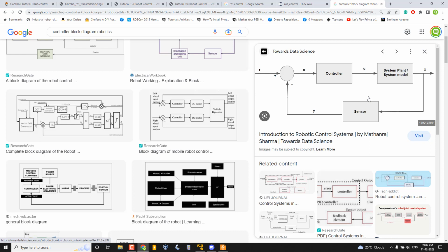You can try with your hand. Currently your hand is in one position, and if you quickly move to another position, that is not the desired kind of motion that we want in robots, right? If all the motors are moving very quickly, the robot will be shaking, right? So what we want is a smooth motion. If you give 90 degree, there should be some kind of acceleration and deceleration that we give to the motor to obtain the smooth motion. Because when you start the motor and when you stop the motor, it should be smooth. So that is the main purpose of the controller.